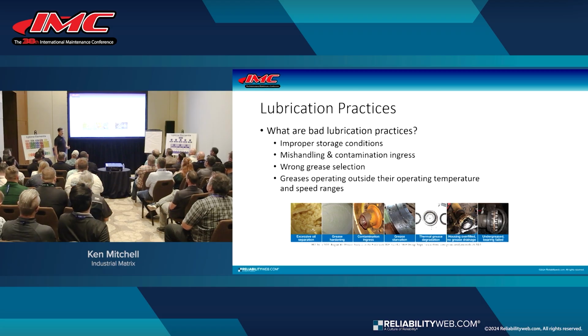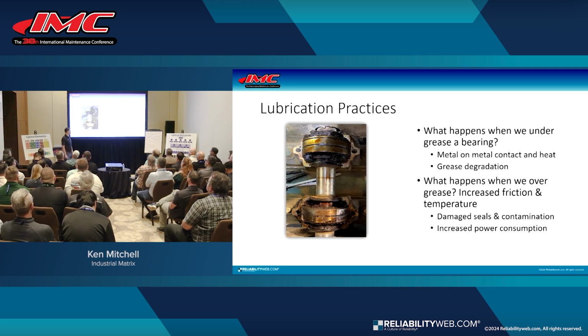Obviously, contamination is a big issue. We look at grease selection and greases operating and doing really what they're designed to do. I've seen it time and time again where we put a standard lubricant in, but perhaps the bearing calls for a high temp grease, or we're not putting in a lithium grease. Mixing greases can often give us more of a headache than not putting the right amount of grease into that bearing to begin with. So we really need to start with good lubrication practices.